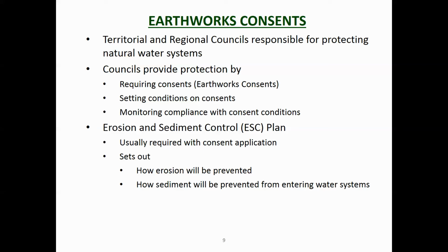You need a consent to do earthworks in New Zealand, and they set conditions on those consents, and one of those conditions is that you install erosion and sediment control measures. That might be practices that you're going to do. You're going to open up only a limited part of land, and also things that you're going to install, like sediment ponds and silt fences and so on. And they also monitor compliance with the consent conditions.